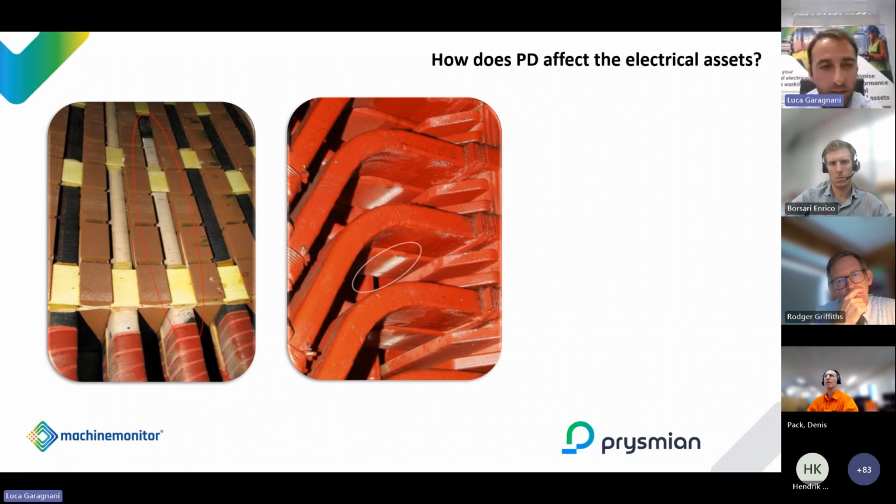Another picture of our rotating machines where we can see the effect left over of the surface discharge on the grading system. And exactly the same, we can see a perfect line where you see the slot coating transition between the slot coating and the bar without screen. And in this case as well, there was an issue with the grading system that created this white mark.